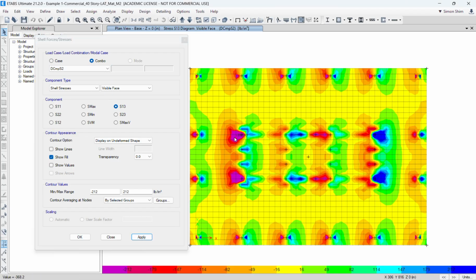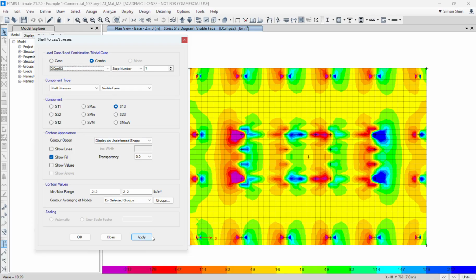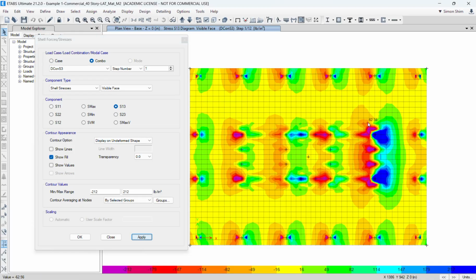S2, you see there's some local stress concentration, and including the wind effect, you'll see another higher shear stress at the corner, especially on the suction wind blowing. It creates some significant shear stress, which makes sense, right?